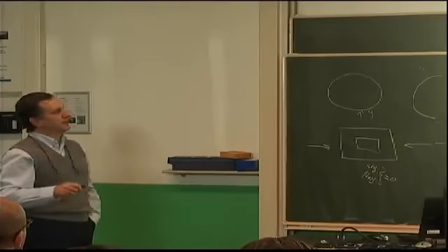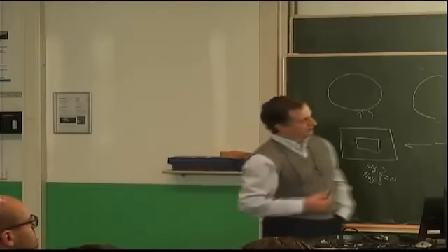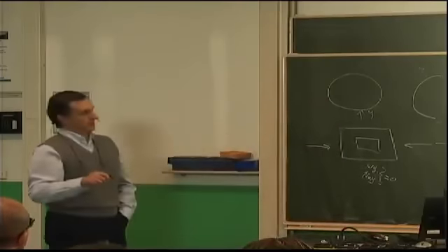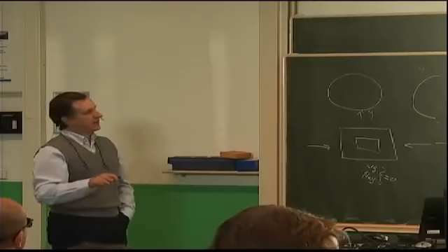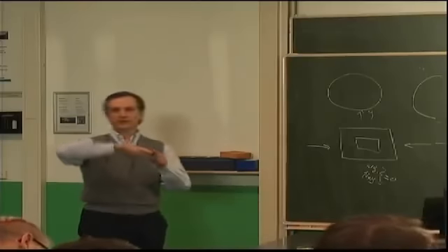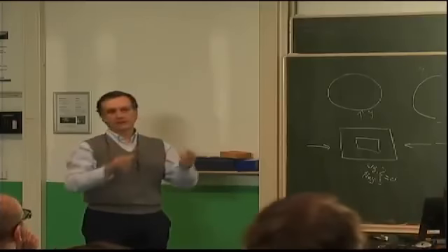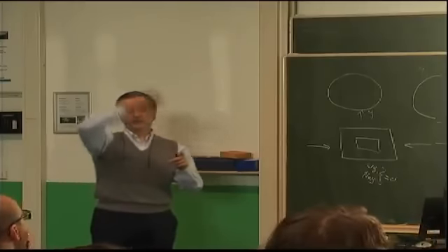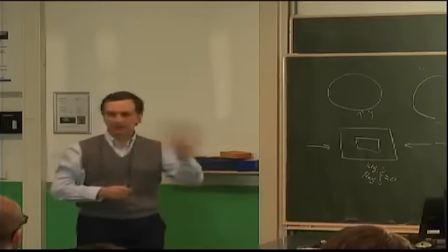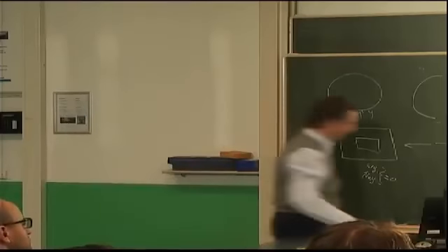And notice the M and N. Now those are important. Let me briefly mention them now, and we'll talk about them some more later on also. This is my M and this is my N. Sine M pi x over A basically means a function that between 0 and A just simply does one half wave. So if M equals 1. If M equals 2, then between 0 and A I will have two half waves, and so on. So the M and N is the number of half waves in the different directions, in the X direction and the Y direction. So if I have a plate